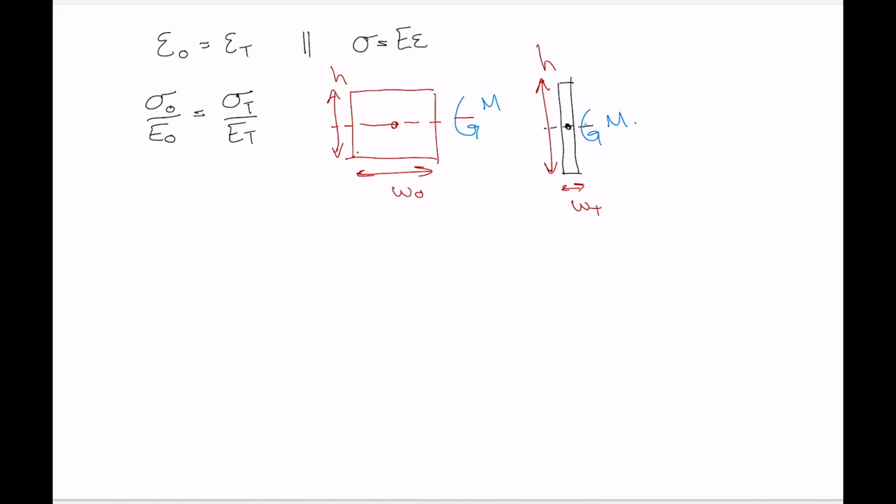Okay. So the stress in the original filler material is given by our bending stress equation. We have M y over I for that original untransformed material, and then we're dividing by the modulus of elasticity there. And for the transformed beam, remember, we're considering the stress at the same location.